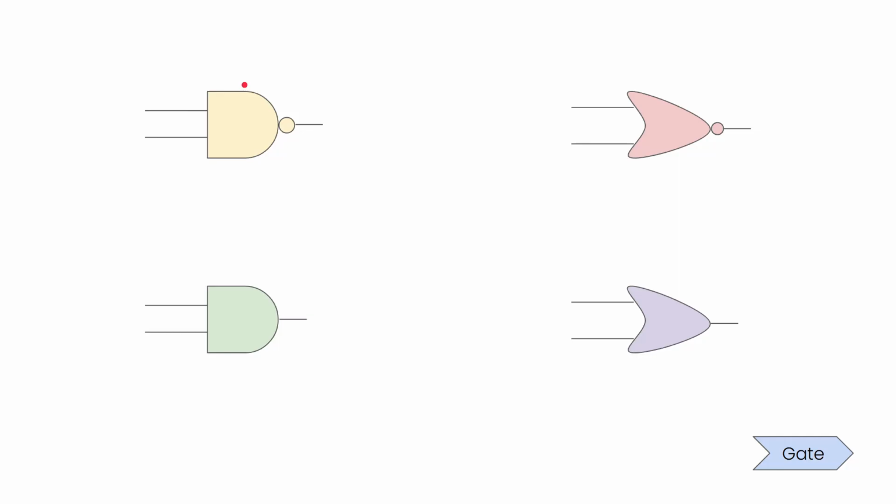But the more complicated version is that different gates can have different propagation delays, how much time it takes for the input to change the output, how much time it takes for the gates to do their jobs. They can have different sizes. They can consume different amounts of energy. And so there are different styles of design to even implement, like a NAND gate.